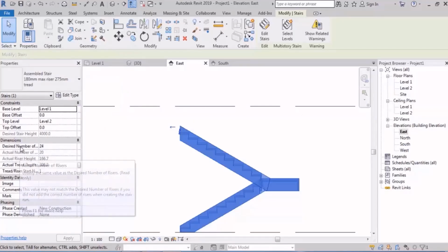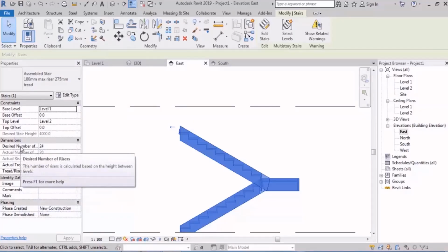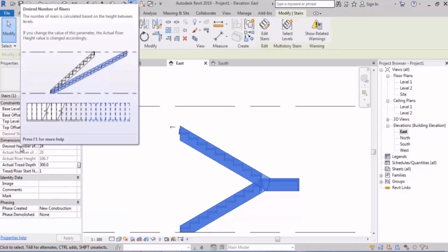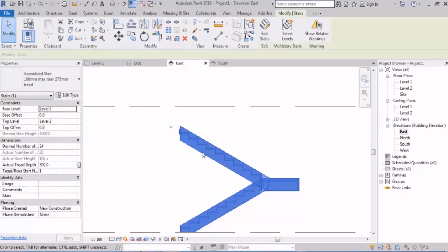I told you that unjoin messages of Revit are not important at all. Alright, so if you keep a piece of that here so that the connection is still there, and then you draw that arc, you can do it. Alright, this is the trick. You keep a piece of it there and then draw the arc. If you do this, you will not face any error.